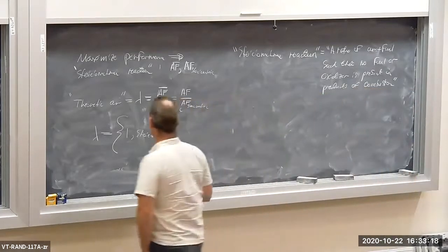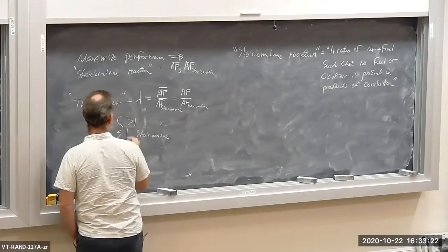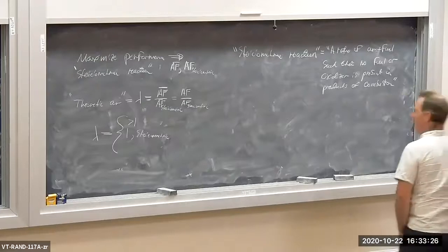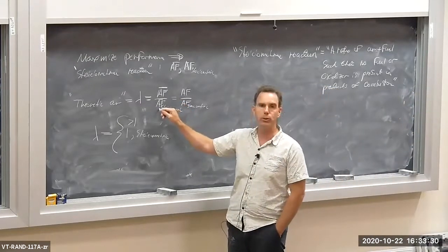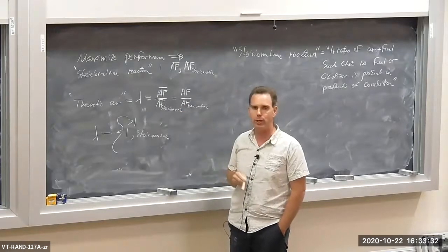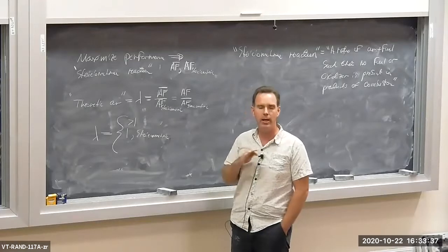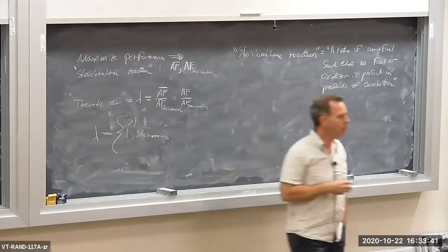Now, lambda can be greater than 1, so we can be greater than 1 as well. We can be equal to 1 or greater than 1. If lambda is greater than 1, that means the actual air-fuel ratio is greater than the stoichiometric air-fuel ratio. That means we have excess air. We have more air than fuel, more air than we need for the given amount of fuel that we're trying to burn.